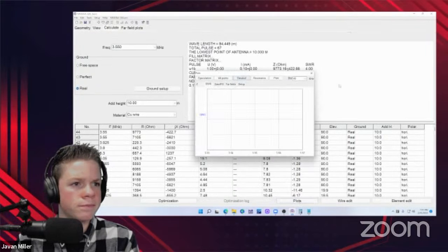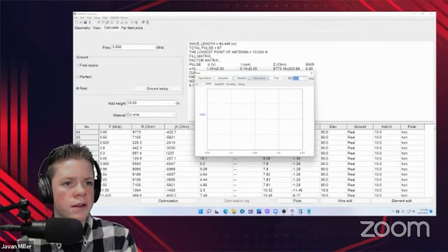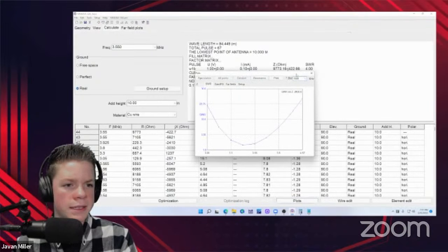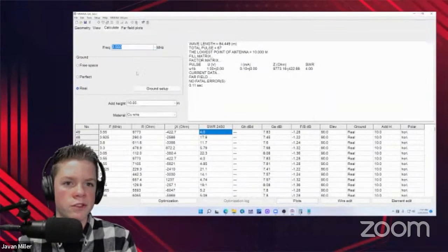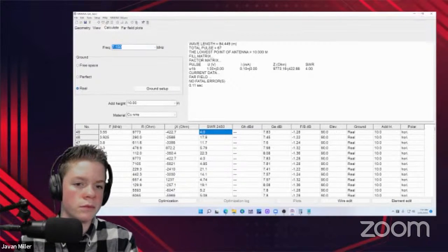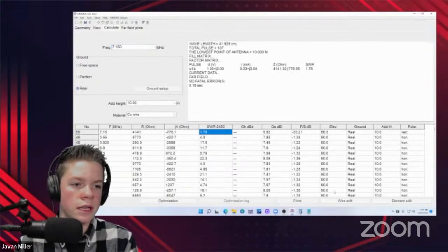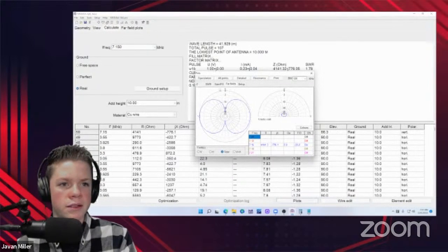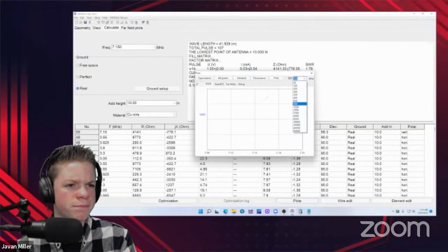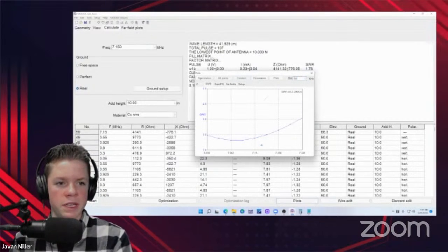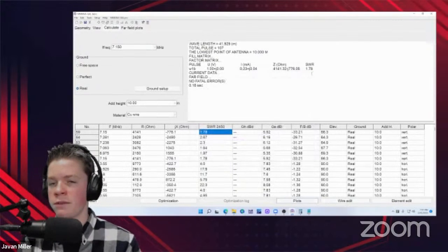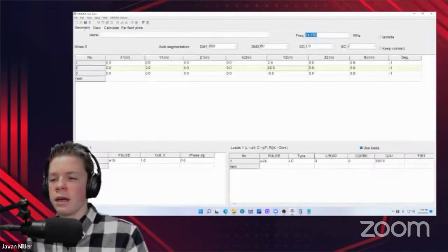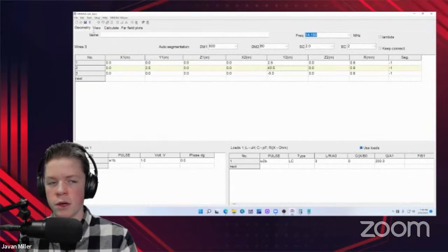Let me see what it's like on 80 meters. My guess is it still didn't make that large of an impact. Let's go on to 40 meters to see what happened with this change. Let me run another scan and see where it put the dip. So yeah, shortening that helped a bit, but I think we can shorten this even a little bit more, which will help all the bands. All of them still have a little bit of a low resonance.